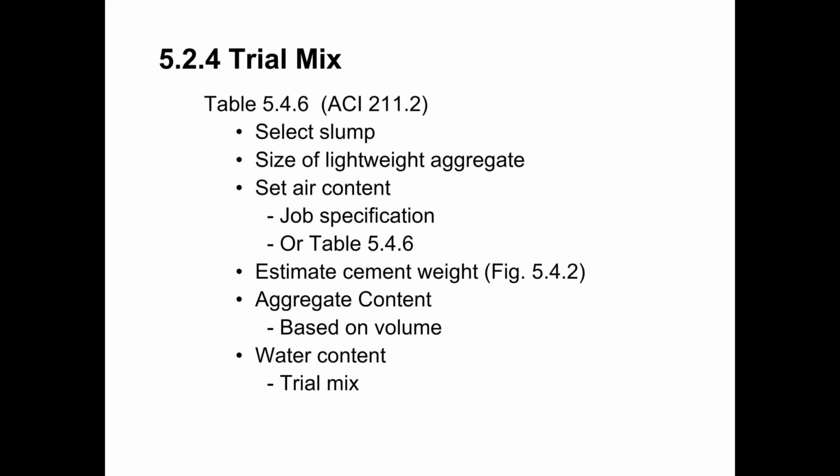So it's not very specific at all based on your cement content and your compressive strength requirement. It gives you a pretty broad range that you could choose from. So again, the 211.2 process for a lightweight mix design is even less precise than the process that we've been talking about for a regular weight aggregate mix design.